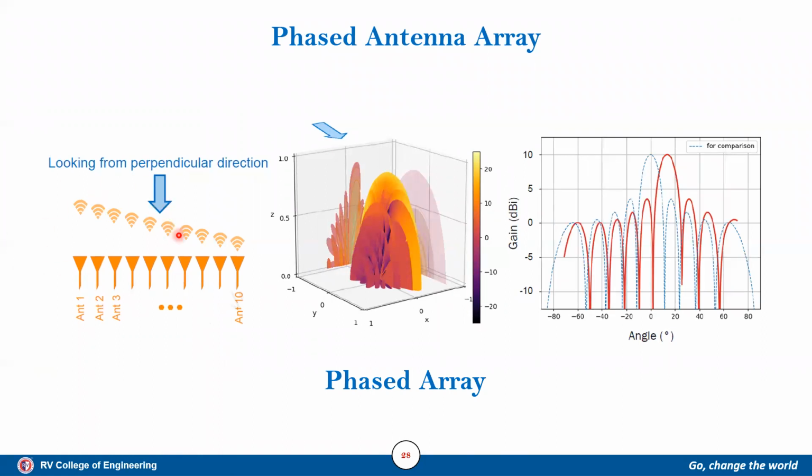Now, when we provide phase shifted copies to the different antennas, the direction of the main lobe is steered or rotated to a particular angle. So now we can see this is the projection of the three-dimensional radiation pattern on this particular plane. Whatever we are seeing in the red color is after giving the phase shift. For comparison, we can compare with the 0 degrees, where unshifted copies are provided to the antenna array. Now we have a separation, which means the direction of the main lobe is steered. So that's why this is an antenna array: when we provide different phase shifted copies, we get the steering capability. That's why this type of antenna, in which we can steer the beam by changing the phase of the signal provided to each antenna, is called a phased antenna array.